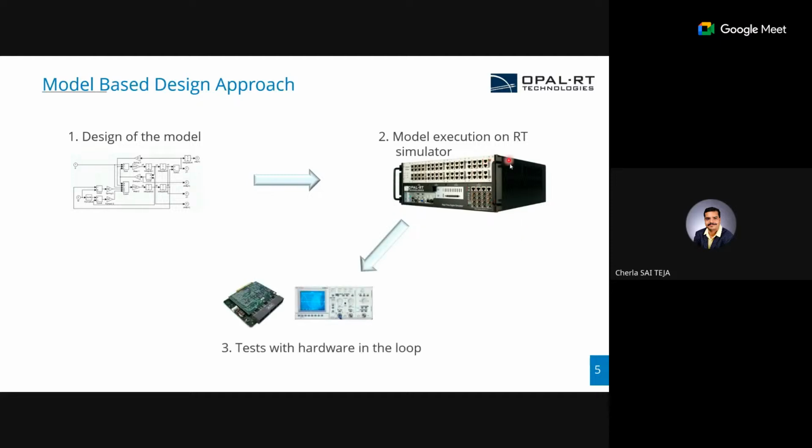Each and every target has analog and digital channels using which we can connect to an external physical controller. This setup is known as a hardware in the loop setup. Then, depending on the communication and the results we get from the plant and the controller, if we find an issue with either the plant or the control, we can go back to designing the model and recalibrating the controller or the plant till the desired results are achieved.